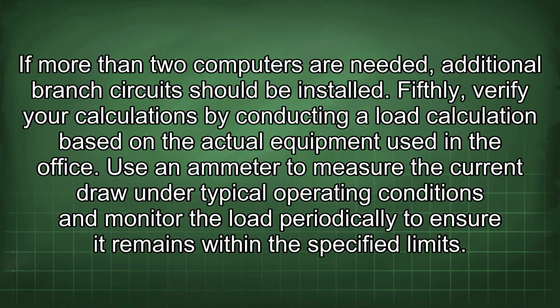If more than 2 computers are needed, additional branch circuits should be installed. Fifthly, verify your calculations by conducting a load calculation based on the actual equipment used in the office. Use an ammeter to measure the current draw under typical operating conditions and monitor the load periodically to ensure it remains within the specified limits.